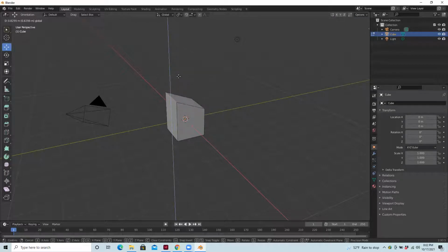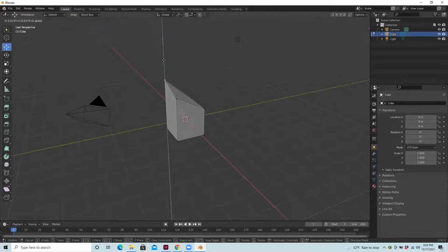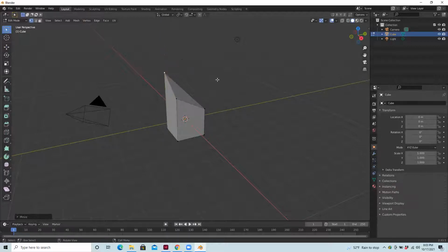So maybe we can begin to see that one approach is going to be altering objects, but just working on individual parts of them. I think I'll just try one more example. What if I switch to vertex select, and I think I'll select this top rear vertex. And I could use the shift key to select multiple points, just by the way. Let me go back, and I want to just select one point. And then I think I'll just pull that one up higher. So I'll use the blue line with the move tool still active. I think I'll switch back to select tool.